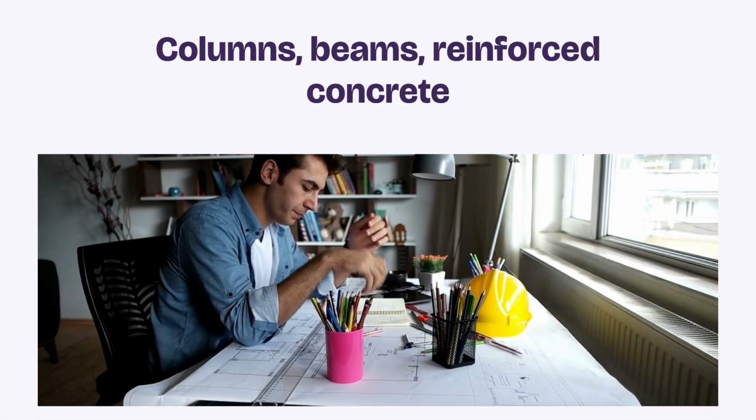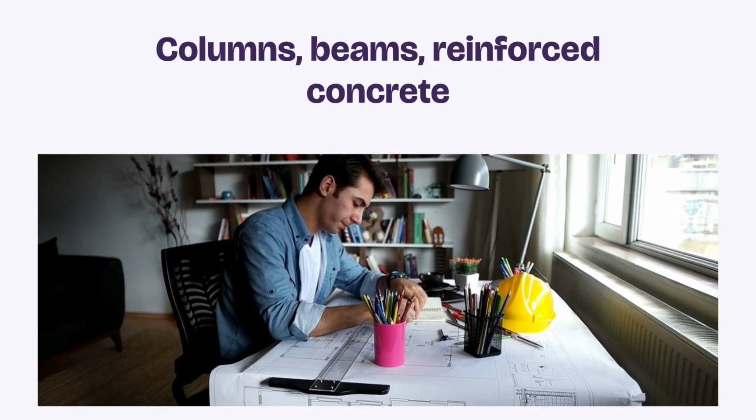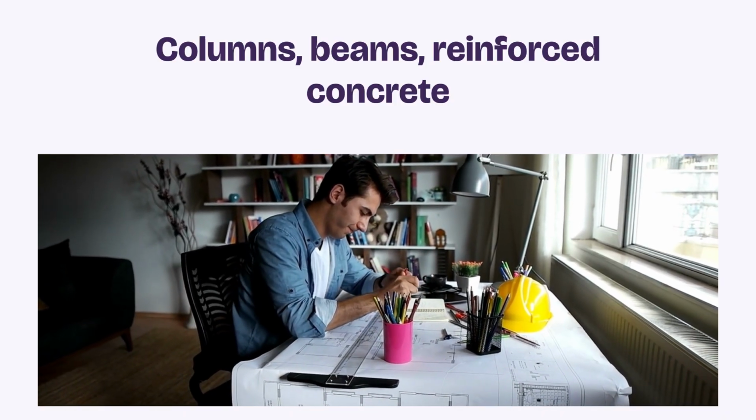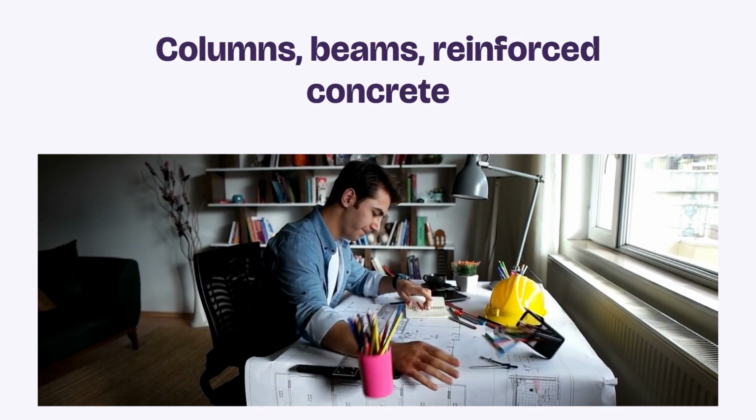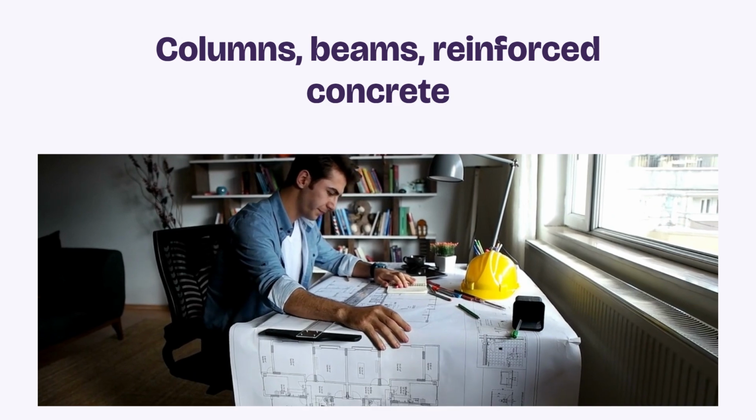Structural elements have their own marks. Columns are shown as filled or open circles. Beams might look like thick lines or rectangles, sometimes annotated with B or their size. Reinforced concrete is often identified with stippled or cross-hatched areas.